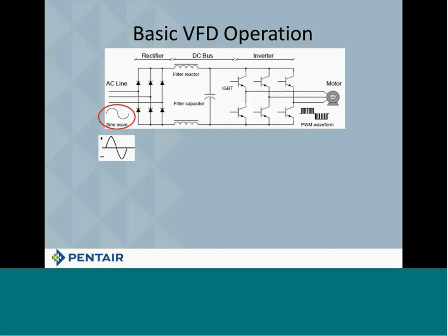If you're going to put single-phase power in, the point to remember is you have to allow for double the amperage of the load that you're trying to move. Okay? So now I go into the drive and I go through something called a rectifier. And what the rectifier does, it takes that plus and minus sine wave on the AC signal going in, and we run it through a DC bus, and you can see it cuts it in half and turns it over.